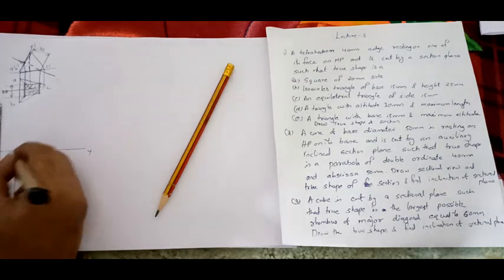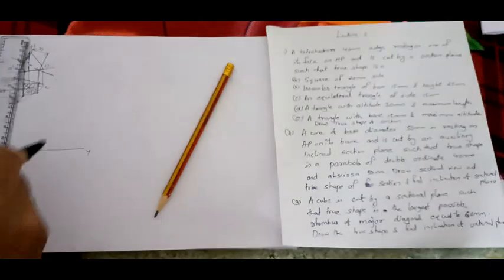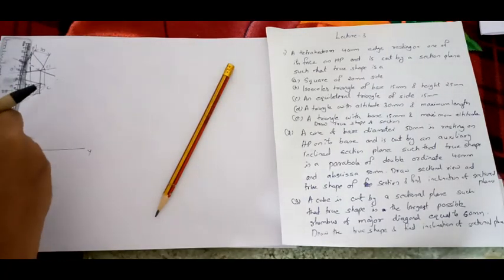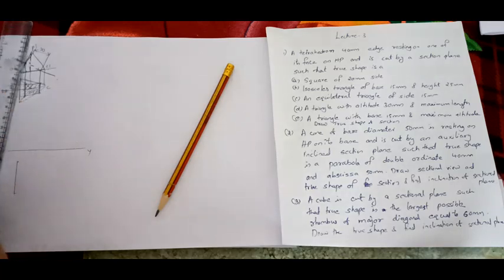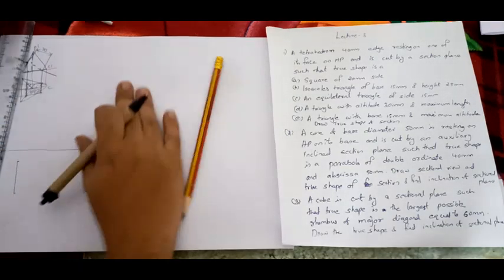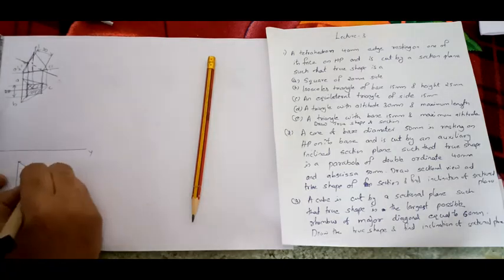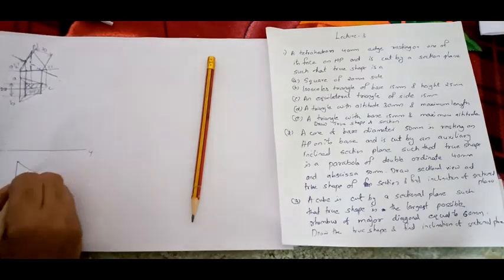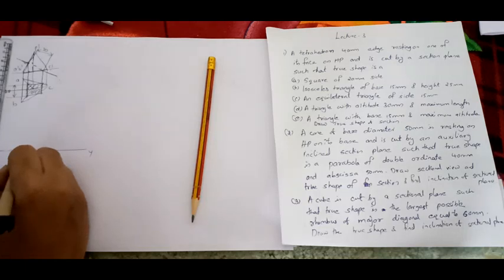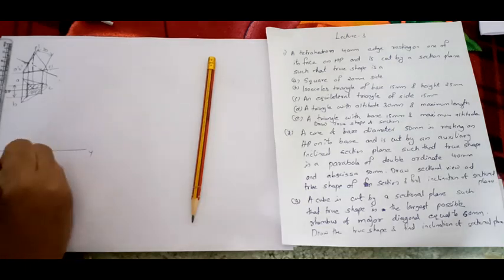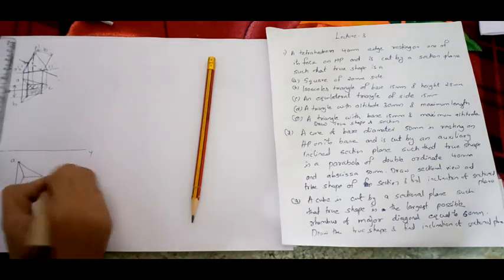Now what you have to do, take 40 mm on compass, right? Take this 40 mm on compass, and complete the tetrahedron, or take 60 degree and complete the tetrahedron. Now what you have to do? See, you can complete this top view. Now this one is your A, this one is your B, this one is your C.